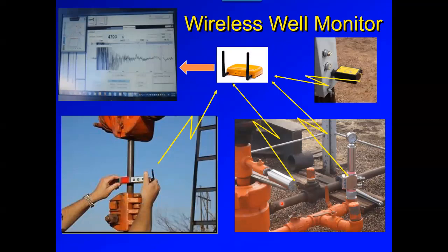Now, with that being said, one of the benefits of utilizing the wireless equipment is the simultaneous acquisition. As you can see demonstrated here with the fixed power adapter and the power probes, as well as the remote fire gas gun, which we talked about yesterday, the wireless pressure transducer and the PRT, you have the ability to acquire all this data simultaneously. So we can record power, we can record dyno while acquiring power and pressure, recording the tubing pressure, as well as shoot a fluid level. And you can see from the TAM image here we are shooting a fluid level while recording a dynamometer. So from an efficiency standpoint, it really makes it quite nice, not having to trip over cables as well as acquiring things simultaneously. Now, what I'm going to do is jump into the procedures on how we acquire data with the polish rod transducer.